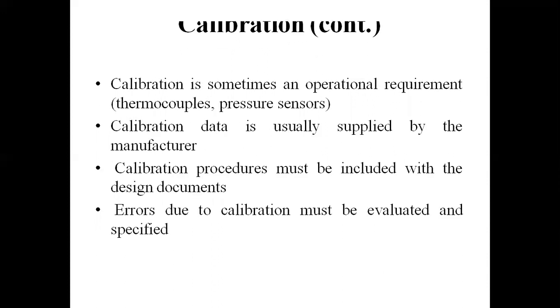When we talk about calibration procedures, we often have two different types, namely primary calibration and secondary calibration. If the instrument is calibrated against a primary standard, then it is named primary calibration. Similarly, if we are using a secondary standard for calibrating other devices, it will give lesser accuracy. This type of instrument is used in general laboratory practice as well as in industry.